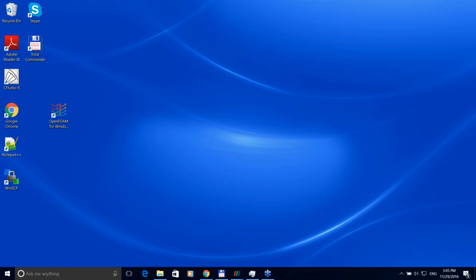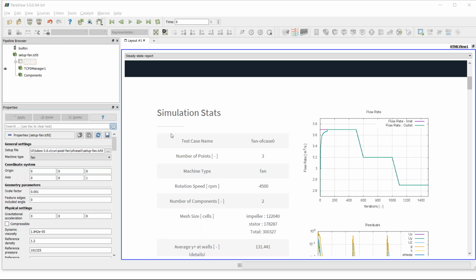Another one, can we use ANSYS files in Turbomachinery CFD for making simulations? Question from Nahale. Actually, yes. You can import the mesh to OpenFOAM, and then you can use it.